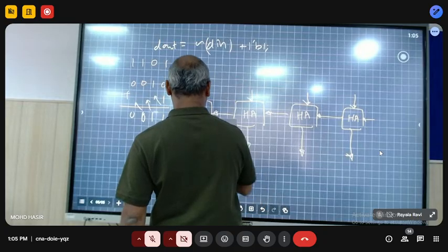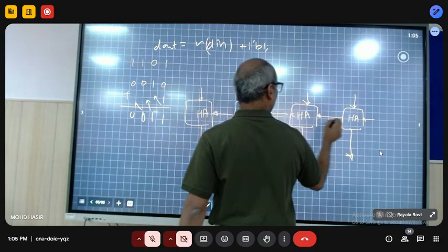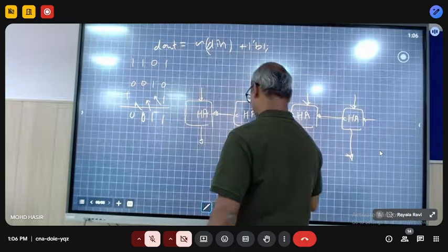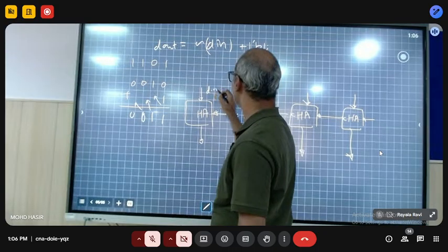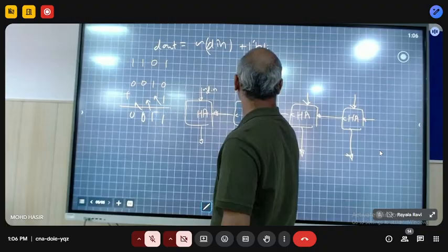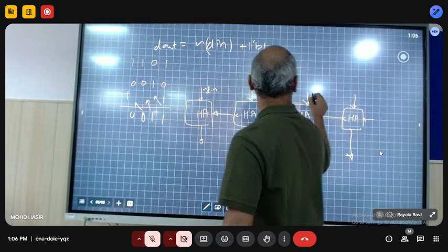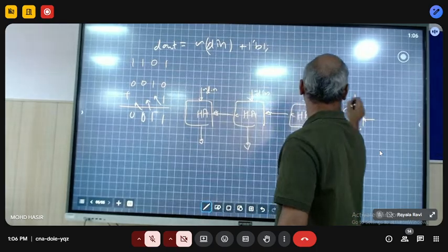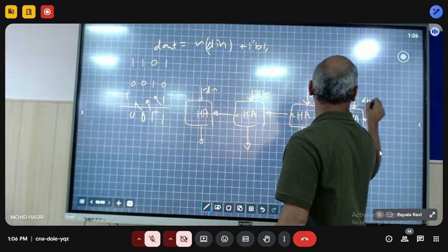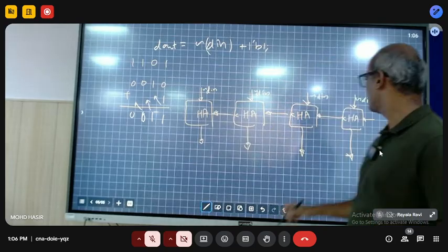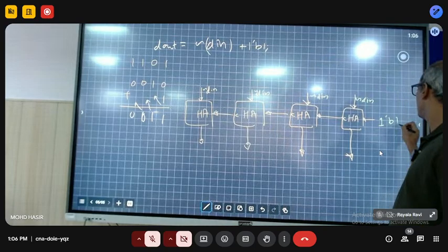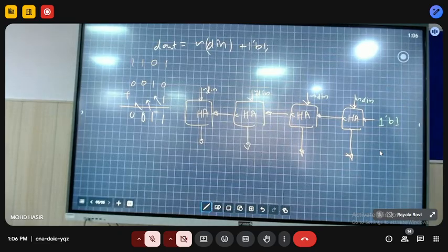If the half adder works, why do we need a full adder? Right? Unnecessarily you are increasing the delay and area. For every half adder there will be two or three more gates, rather an additional half adder plus an OR gate, right, and the critical path also increases.